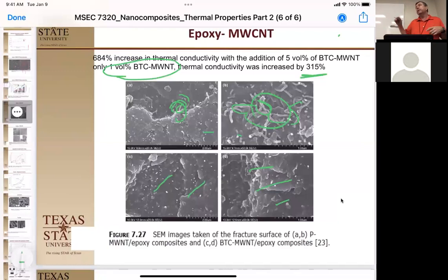And so there is another model that says you have the thermal coefficient of the polymer itself. So it's going to go through the polymer at whatever rate the polymer is going to go through. And then there's an interface between the polymer and the nanomaterial. There's an interface there, and there's a bit of resistance. If you can lower that resistance, then once you get to the nanomaterial, that's usually the highly conductive, and it shoots. The phonon shoots to the end of it, and then it has a barrier where it transfers from the nanomaterial to the matrix, goes through the matrix. And so you can think of it as a series of resistive steps right there.